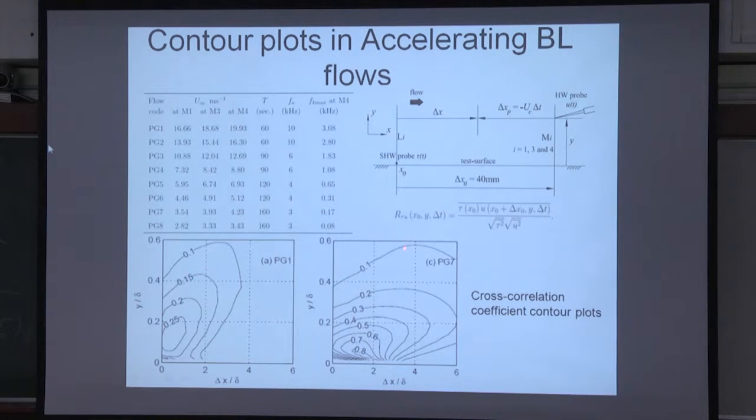All right. Now the more important thing is the other question, so that part is obvious. The so-called sampling theorem tells me I have to sample at least twice that frequency, because you take it through the so-called analog to digital card and acquire that. But you must remember there is an issue here. This is something which I was talking to Senthil about in the morning. There is something called the aliasing error. What is an aliasing error?